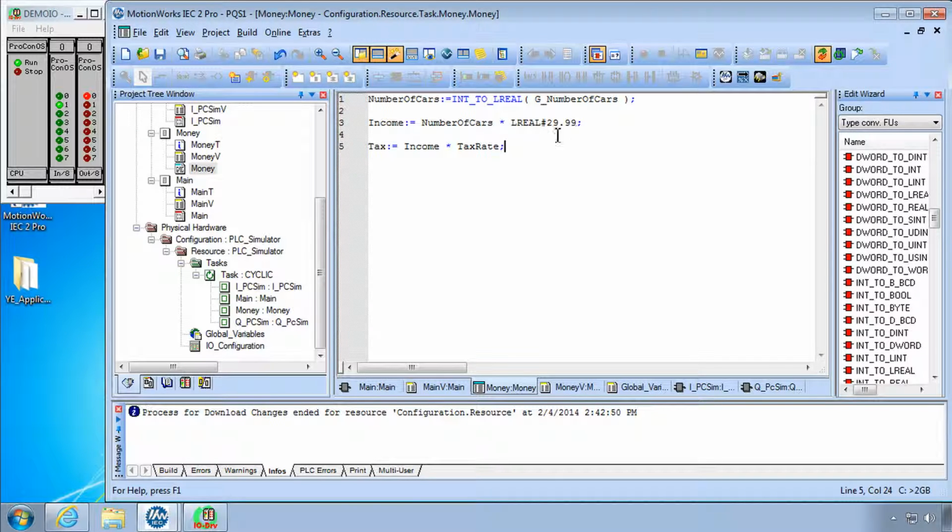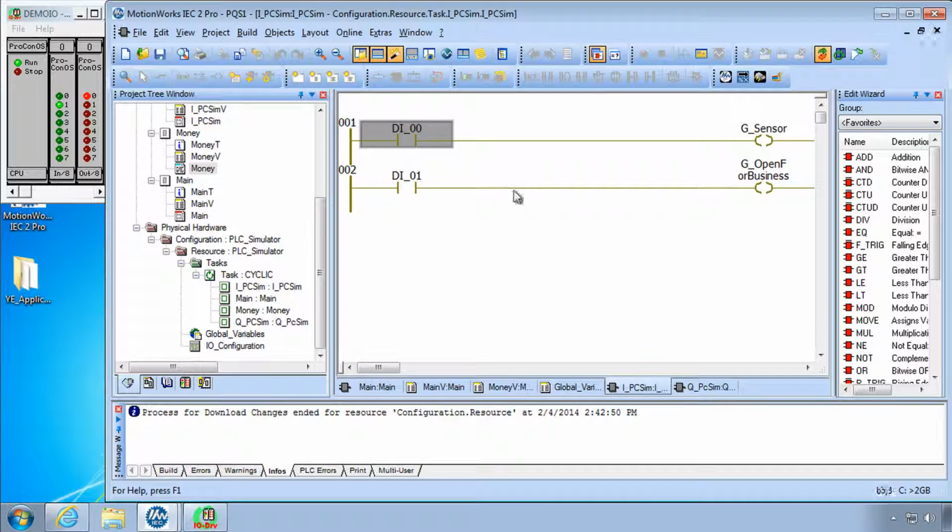On occasion, debug mode will seem not to work. And in that case, what you need to do is to close and reopen the worksheet. That can happen often when you play around with the tasks and their order, or the instances, I should say, within the task or the task order. So if it ever seems like debug doesn't work, close it here, and let's open it again.